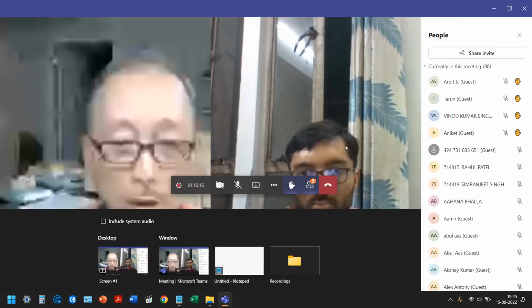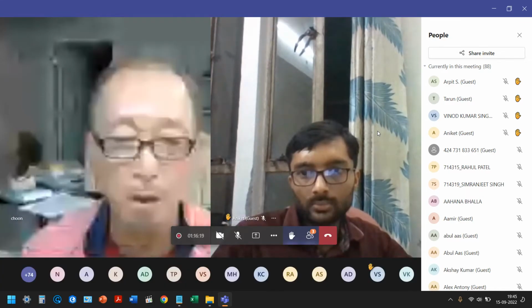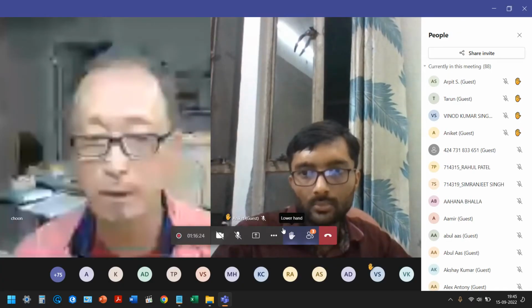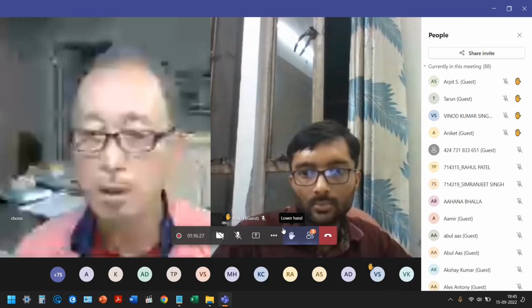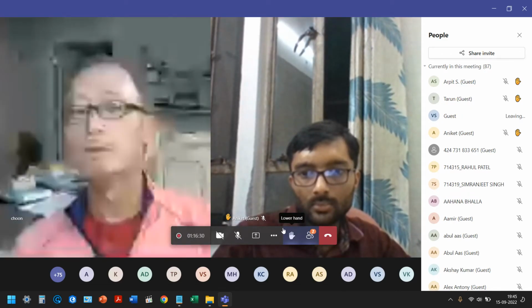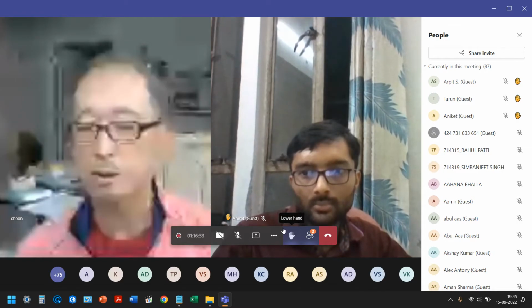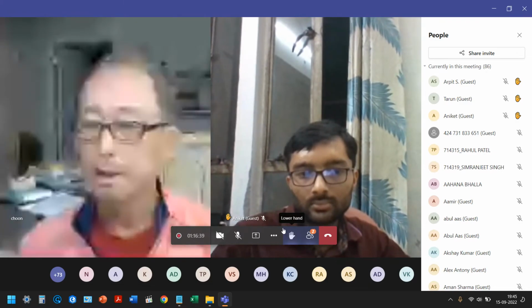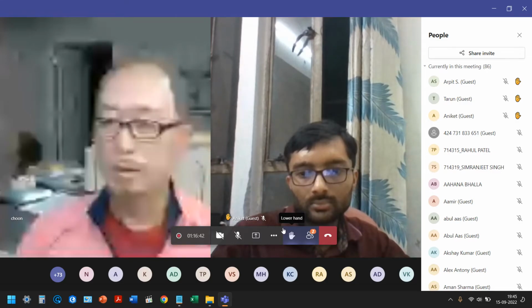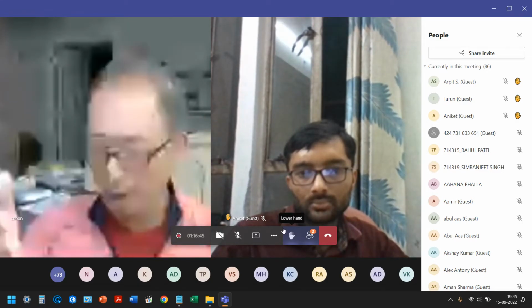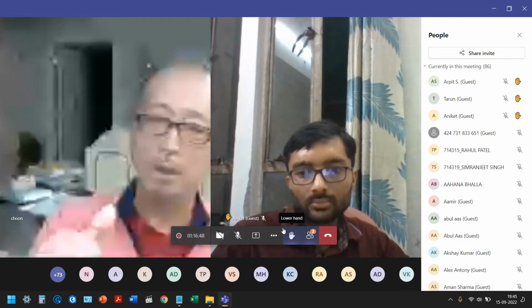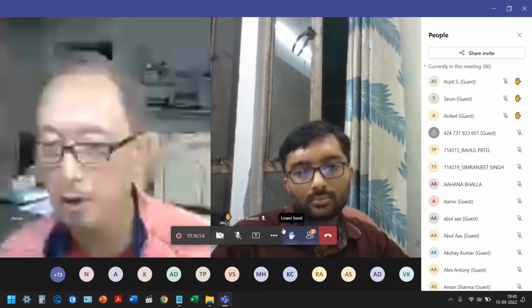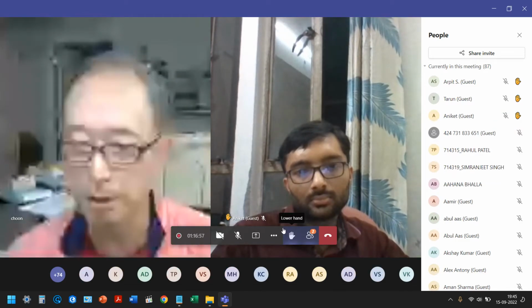Horizontal or vertical, so for 4.5 hertz. If we have acquired data for MASW using a 4.5 hertz phone, can we pick a dispersion curve below 4.5 hertz? Yes, you can. As I said during my presentation, even with the 4.5 hertz phone, it is not a sharp cut. Below 4.5 hertz, the geophone's response curve gradually decreases. So actually you can record all the way down to 1 hertz by using a 4.5 hertz phone.